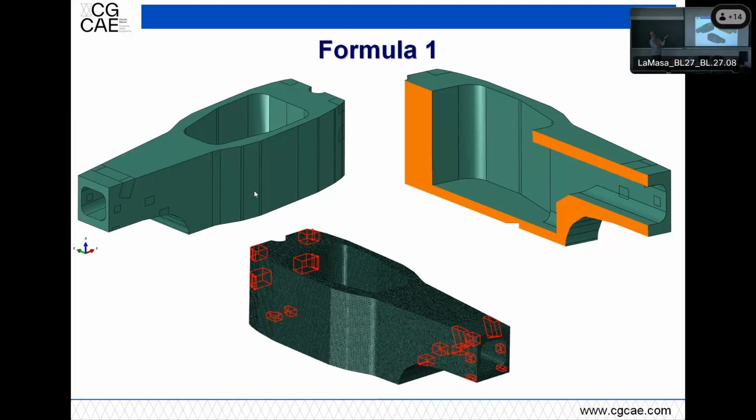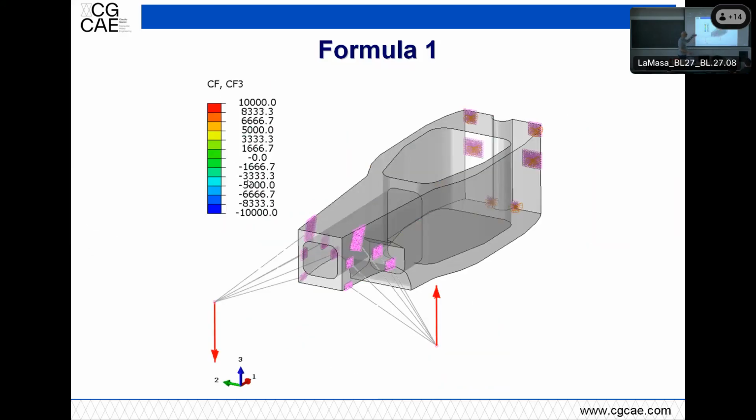This is giving you the optimal structure, and it's doing it for multiple load cases. So what I tried here was to take that monocoque, somehow fill it up, again somehow leaving the space for the driver and the driver's seat and the driver's legs, freezing the connections to the engine and to the suspension elements, and running topological optimization for just the torsional, let's say.